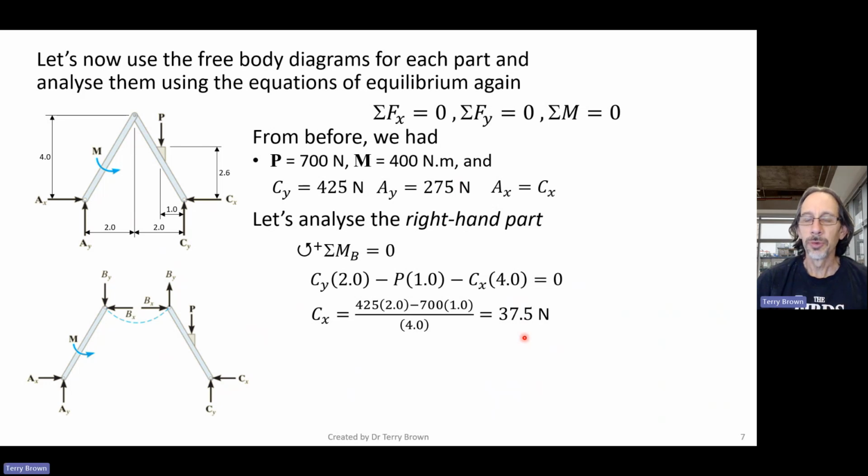Right, so often textbook problems will ask you to do that. In reality, in practice, you're going to want to know the forces at every connection, because if you're designing this thing and at this connection here, you want to transmit that load, you're going to need to know what size bolt or pin to put in there. Okay, so you need to know what the force is here.